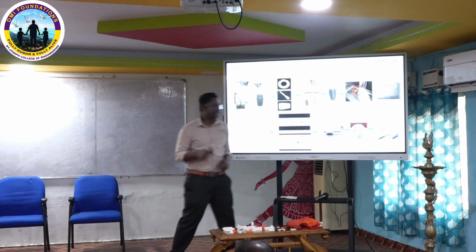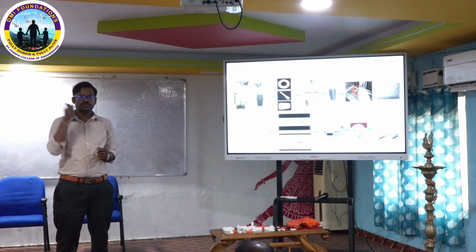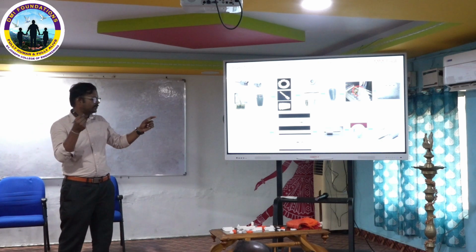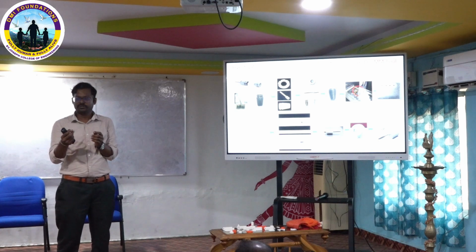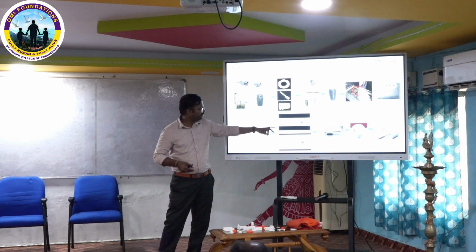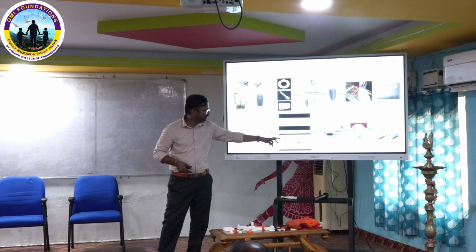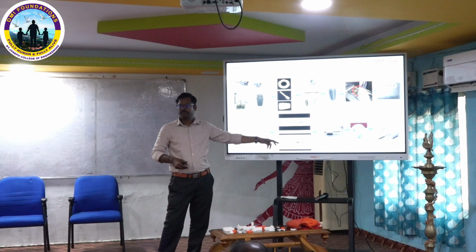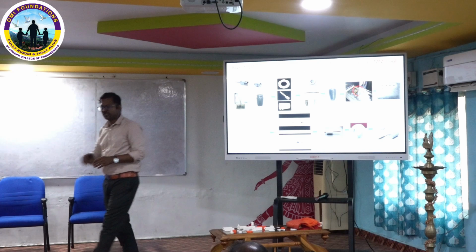That is the top portion. The next one is only the holder. The use of the holder is that when I push the shank into the holder, it tightens the top portion of the collet, so it easily holds the tool. Like that I designed and fabricated it. In the GIF image you can see that earlier I had to place all 3 components and tighten them, but here there are only 2 components and assembly time is also minimal. Then I fabricated and tested with the usual procedure.